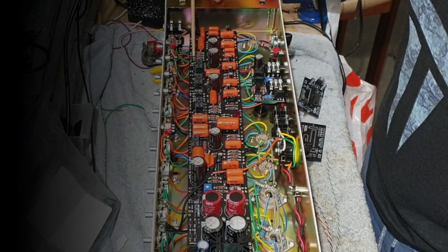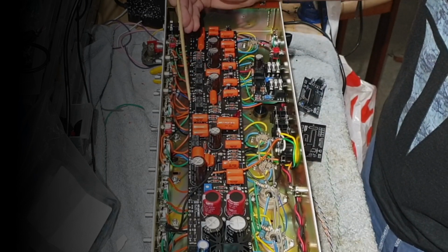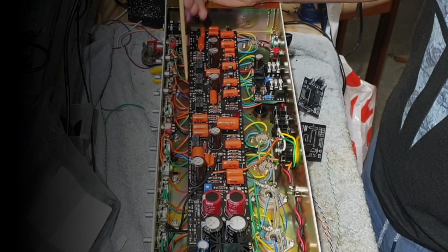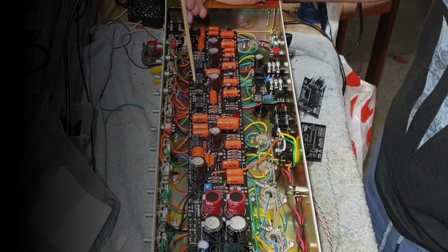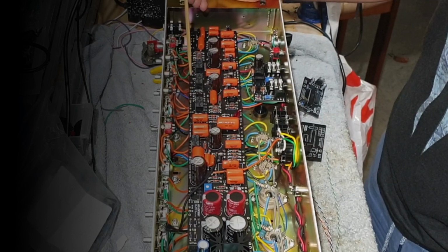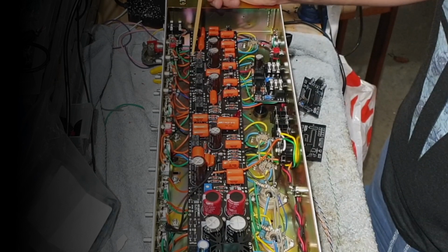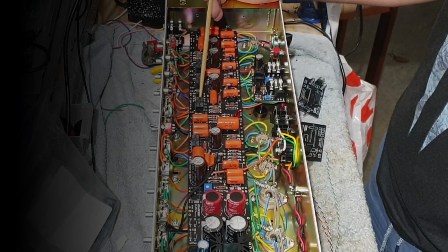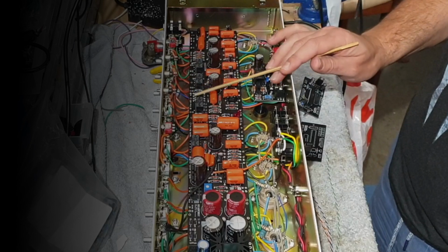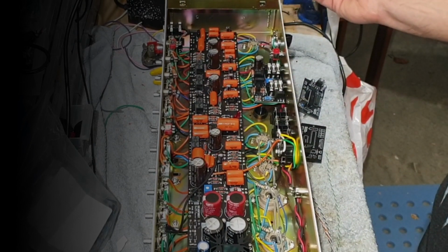So on the board, you've got an R2, an R3, and an R4 pad. And these are the pads that activate the relay coil by grounding. Right, so you've got to ground the pad here, respectively, just chassis ground, and it will activate the coil and then therefore activate the switch on the relay and change the circuit as necessary.